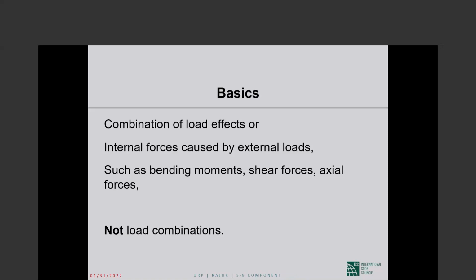We combine load effects, the internal forces caused by the loads, the bending moments, the shear forces, the axial forces. We do not combine the loads. Okay. So when we talk about load combinations, we are really talking about combination of load effects, combination of internal forces caused by external loads, such as bending moments, shear forces, axial forces.